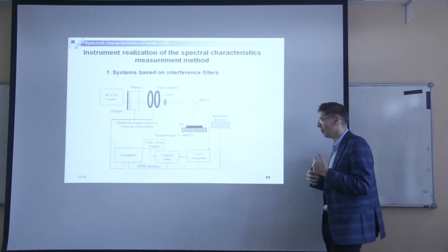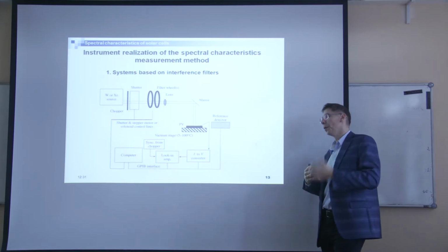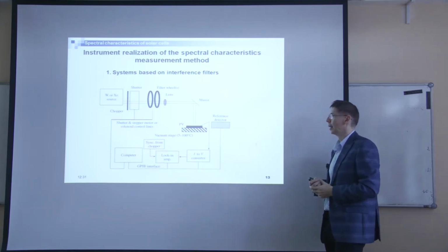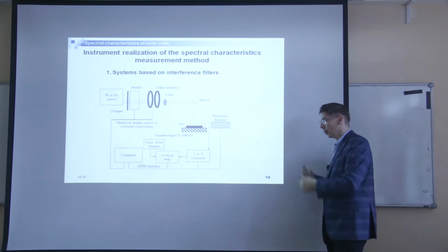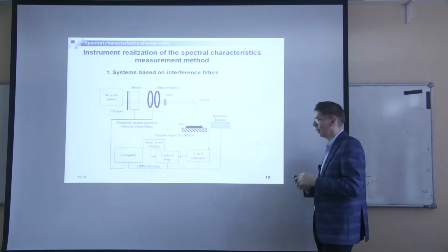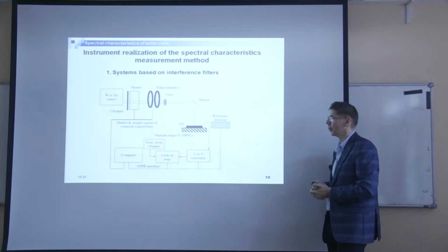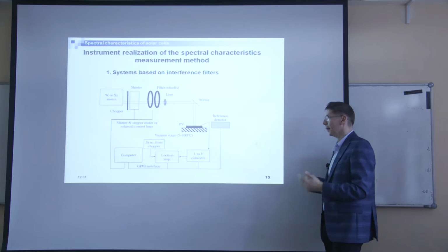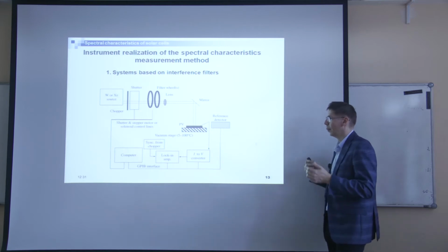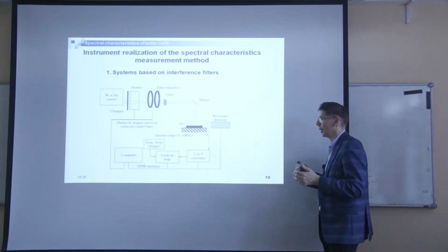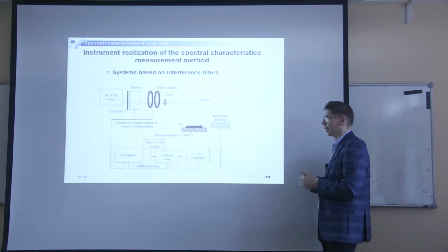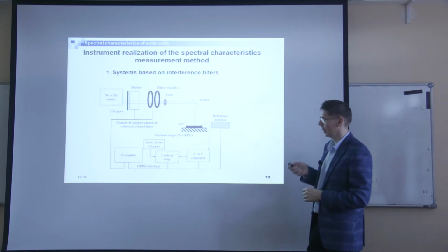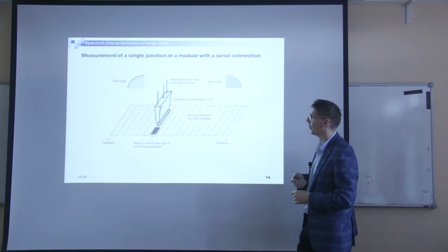it's much easier to measure any modulated or alternating signal compared to a continuous signal, because in this case you are more selective in terms of the noise, so you can really increase the signal to noise ratio.